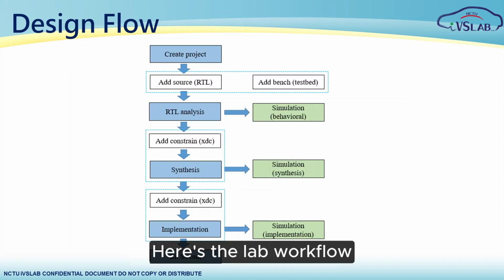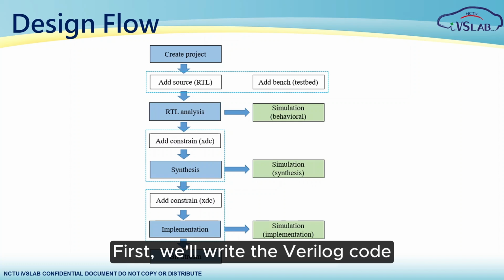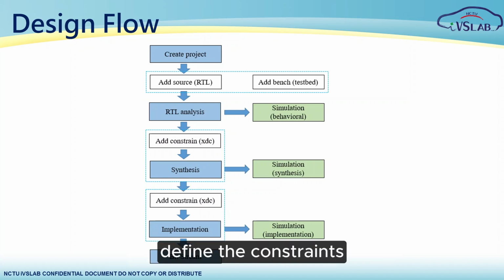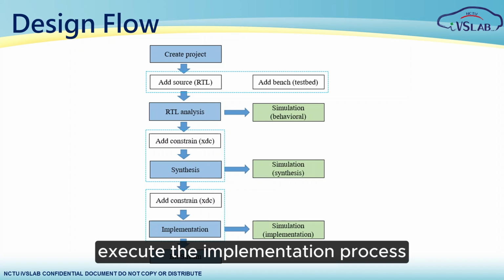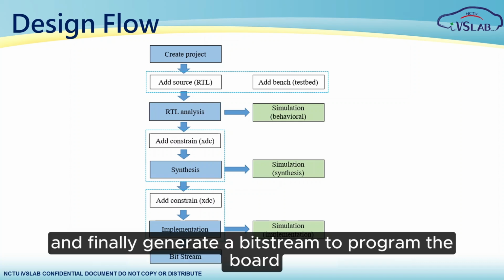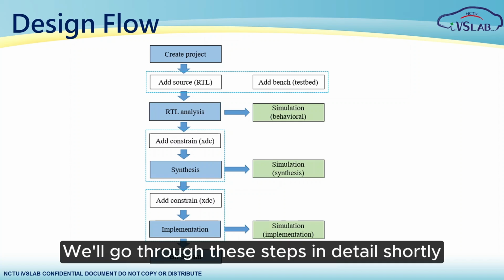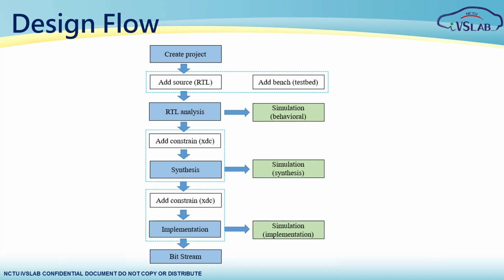Here's the lab workflow. First, we'll write the Verilog code, run a simulation, define the constraints, execute the implementation process, and finally, generate a bit stream to program the board. We'll go through these steps in detail shortly.